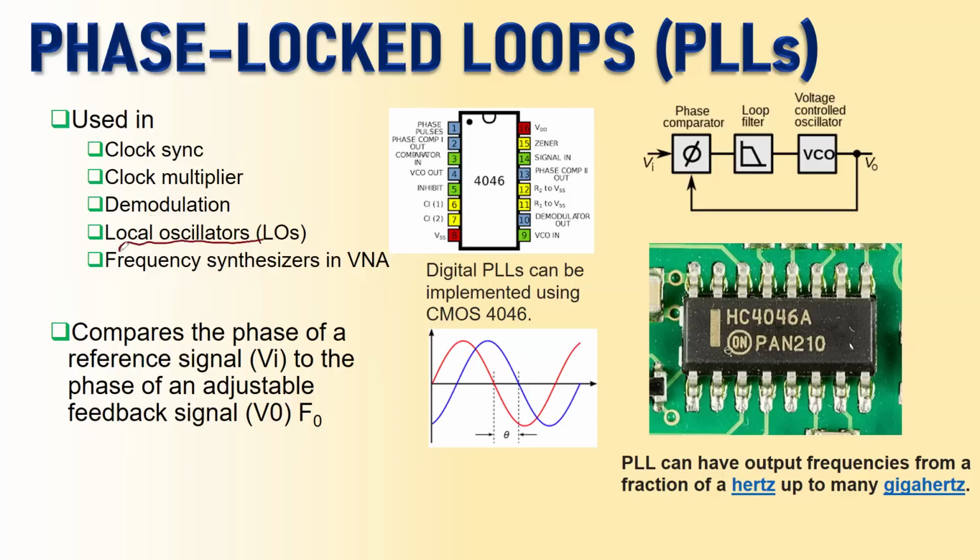Then there is the local oscillator. As we will see now, the local oscillator also can be implemented using the PLL method. Finally, PLL also forms an important block as a frequency synthesizer in a vector network analyzer. So you have this instrument and in that you have this frequency synthesizer, and PLL is a primary block